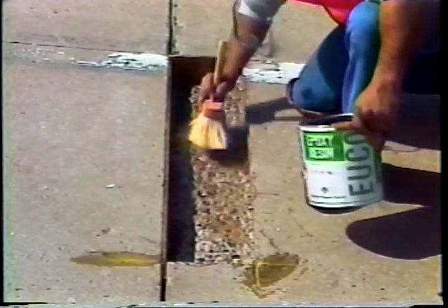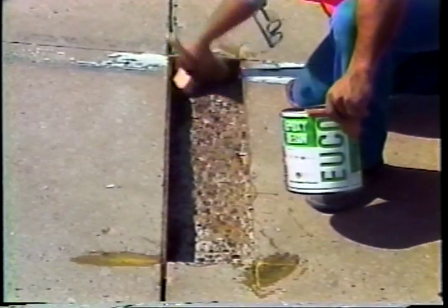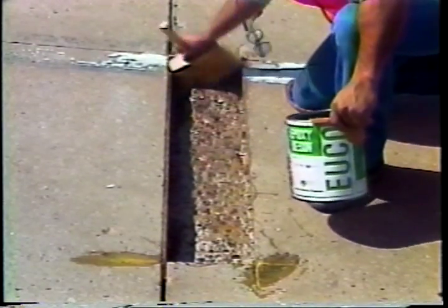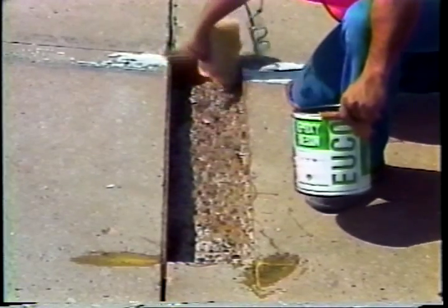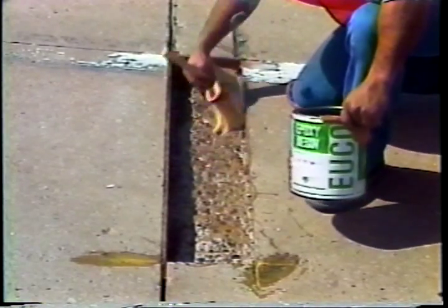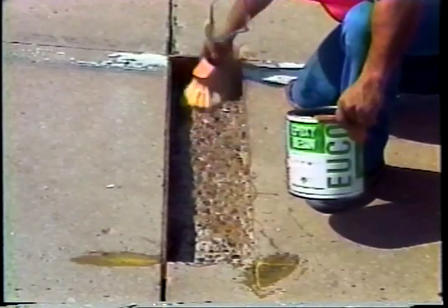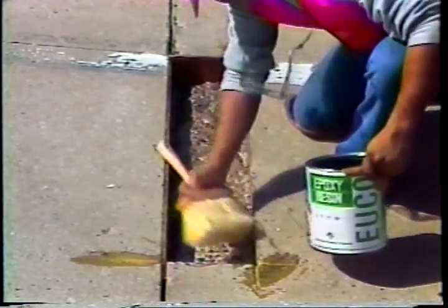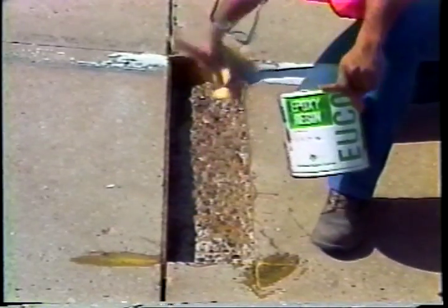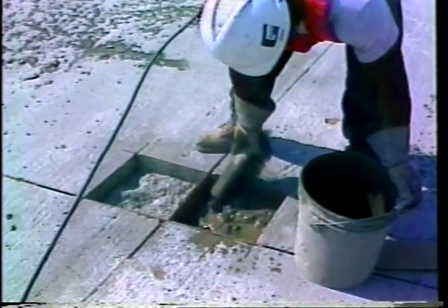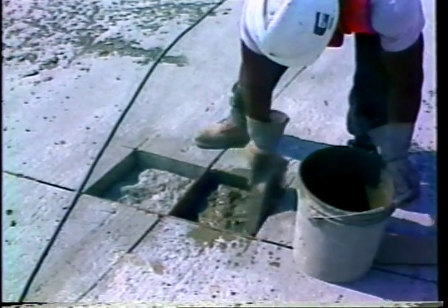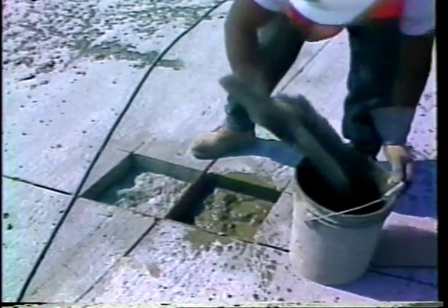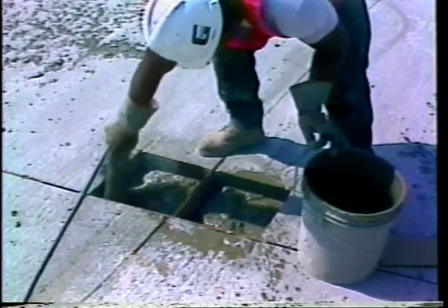Bonding may or may not be required as the last step in surface preparation. It is required when PCC and some of the proprietary materials are used. For these, epoxy has proven to be a successful bonding agent. Sand cement grouts are another type of bonding agent, but are not recommended for rapid setting materials.